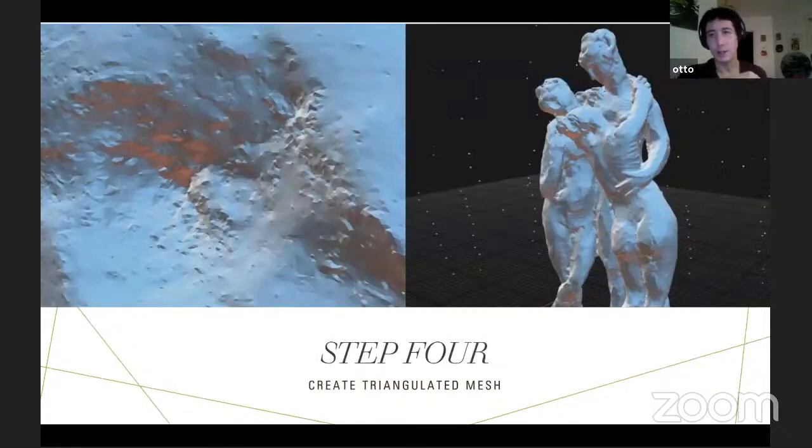So having scaled it, having aligned it, you're then going to turn it from a point cloud into a 3D model. And the way that this is done is basically it calculates a triangle to occupy the space between any 3 points. The reason why it's a triangle is this is the simplest polygon that exists, and actually you can describe pretty much any shape in the universe using triangles.